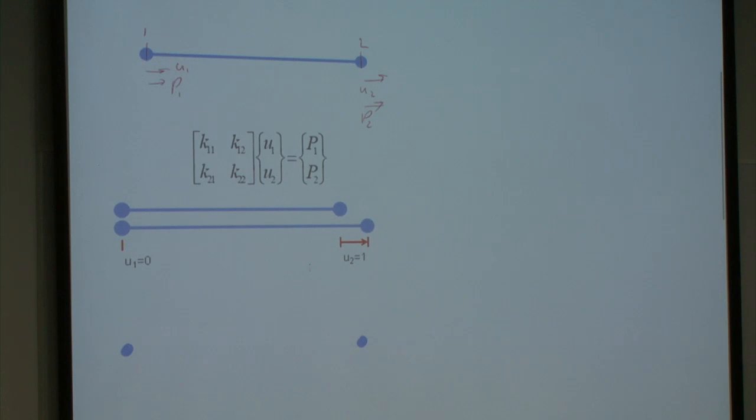They are unknown. So what we can do is displace U2 by a value of 1. This works in whatever unit system you're working with, millimetres, metres. We often work in newtons, millimetres, and MPa in this subject, so let's displace it by 1 millimetre. The question is, what forces then occur?